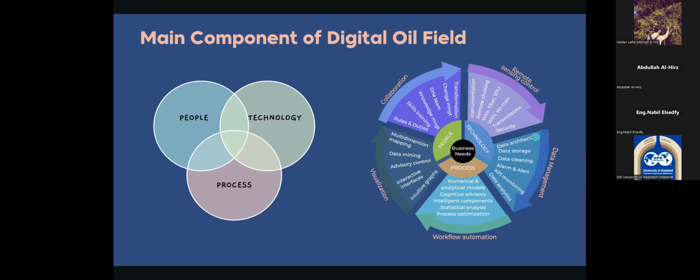And from that data cleaning, we get a lot of spikes. So this sensor is not working as expected. We get a lot of downtime from that sensor. We need to replace that sensor, or we need to check maybe the sensor is plugged because of debris or something like that, so it needs cleaning, or maybe the sensor is not working and you need to replace it, or the battery needs to be replaced with a new one. All that is under KPI monitoring.